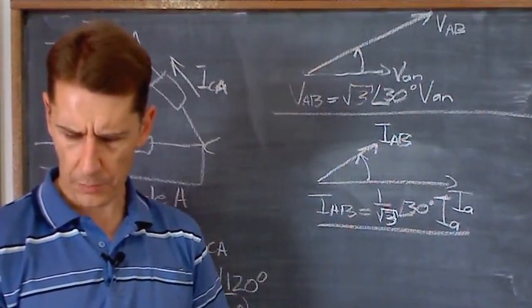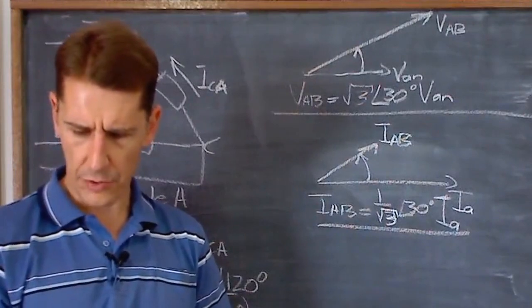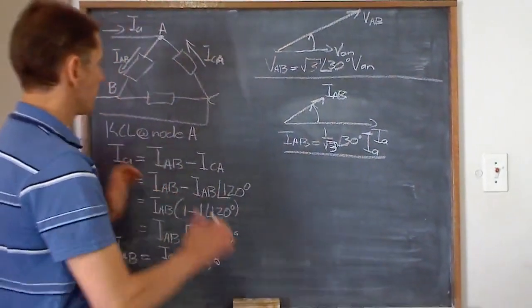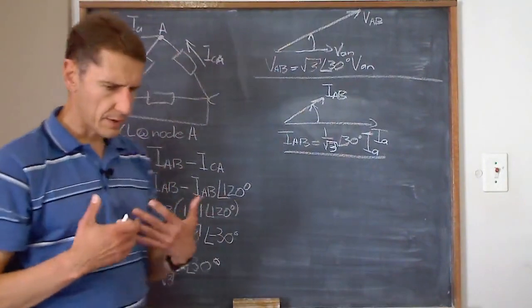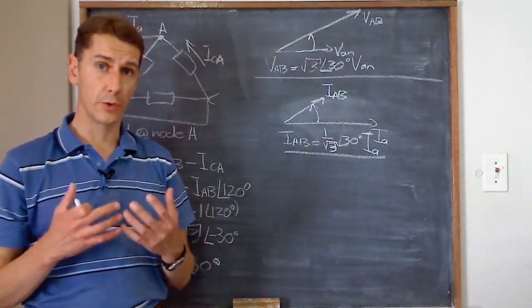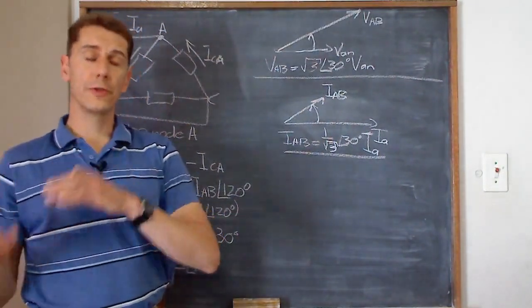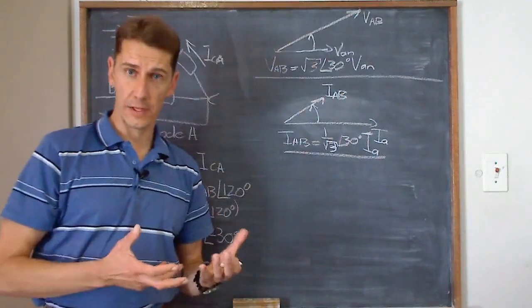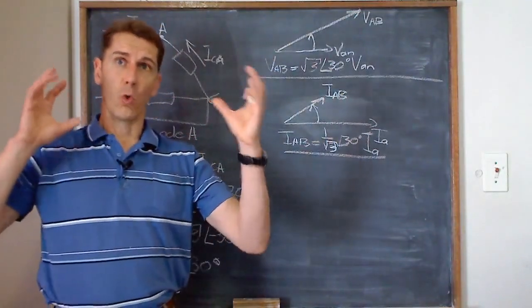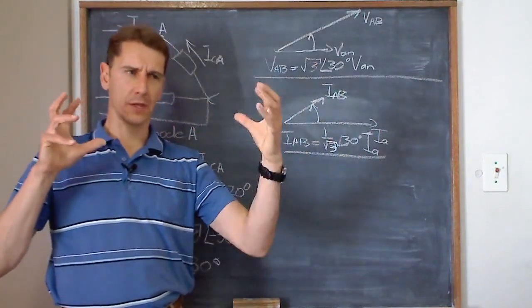All right, a third little point that I see I made on my notes is the transformation. Remember what I said in the previous lecture: when you've got a delta-connected load or delta part in your circuit, we always want to convert that into the Y equivalent, so that you've got a Y-Y connection, not a Y and a delta load on this side.